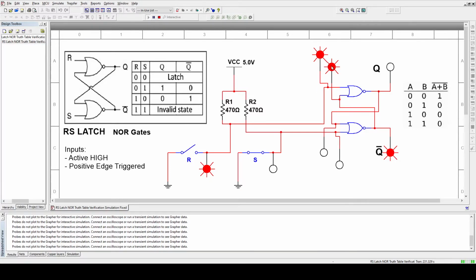1 and 1. If it was an OR gate, if either one of these two goes high, the output would be high, but because we have the inversion bubble here, that high becomes low, so we have a low here. Now the only condition of the NOR gate is if both inputs are 0, then we're going to have a logic level of high or 1. So yes, this one here is low and this one here is low. Of course, we're going to get this condition right here on this other gate.